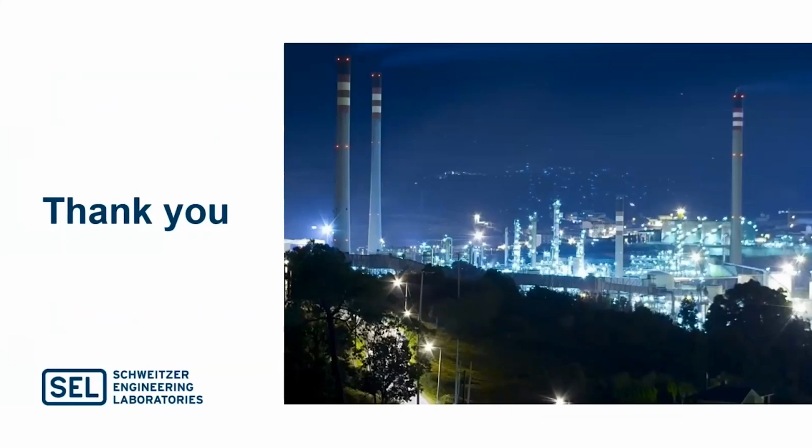We have another question. Which communication protocols can be used with PowerMAX for utilities? I can take that, Tristan. This is Ashish. SEL PowerMAX Utilities RAS can employ most of the industry standard protocols. The communication protocols are selected based on application, as we discussed in our slides, high speed or low speed, analog or digital. The high speed monitoring and control protocols such as IEC 61850 GOOSE, 61850 MMS, DNP, or Modbus can be utilized. If there's any specific project need, we can talk about that as well in greater detail.